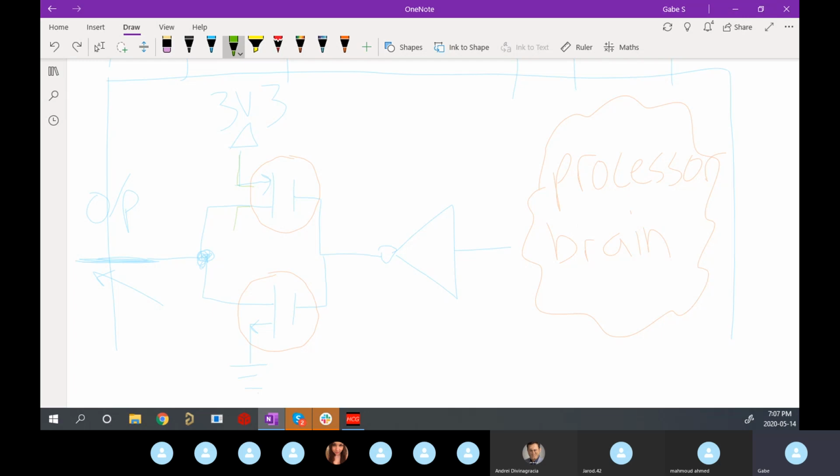Now, the difference between these 2 switches is that, and let's say again, my logic level is 3.3, right? That's our favorite one. The way these 2 switches differ is that if I send a 1, right? 3.3 volts is a 1. If I send a 1 here, okay, a 1 is connected down to here. This switch will close. This switch will stay open, right? They're literally opposites. If I send a 0 here, this switch will close, and this one will stay open. Got it?